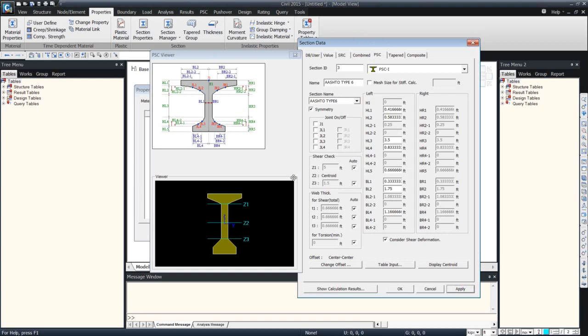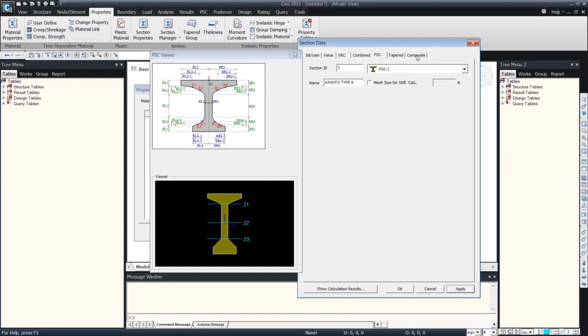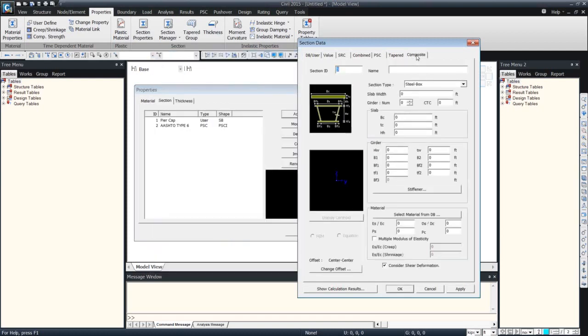Over here, you have multiple options when you model your concrete bridges. One is to define your beam and girder separately. So you can first model your beam and then apply the concrete as a beam element or plate element. Another option that Midas Civil provides you that allows you to do everything at once is utilizing the section called composite type.